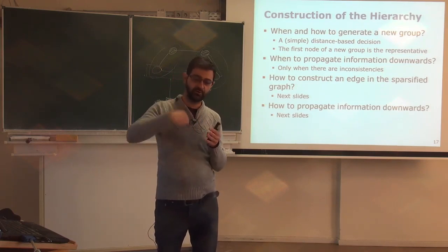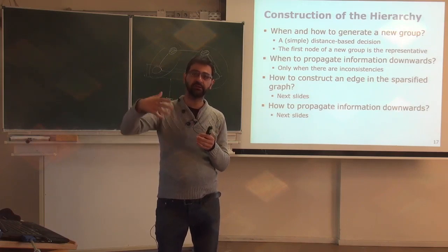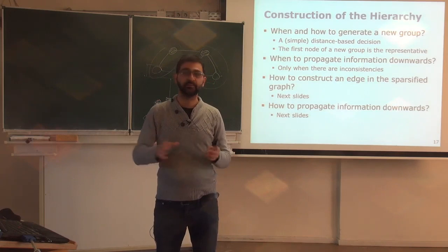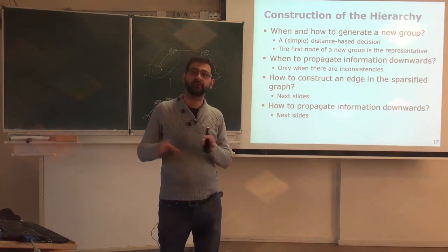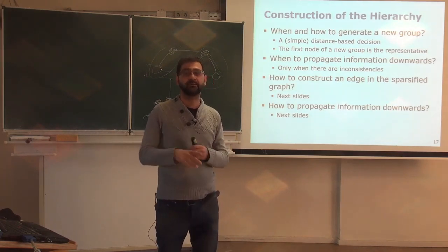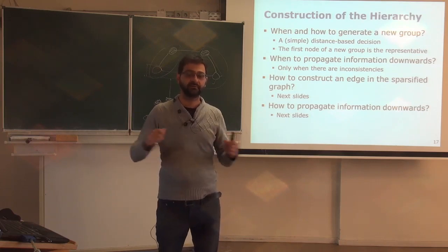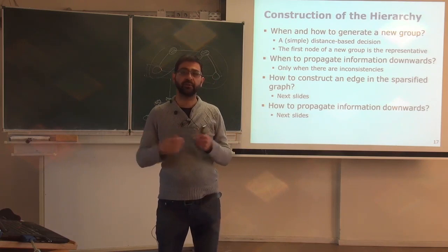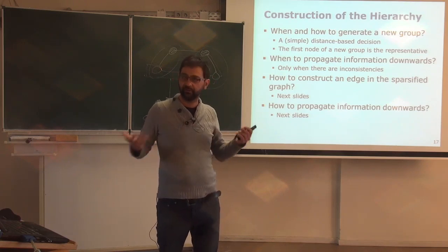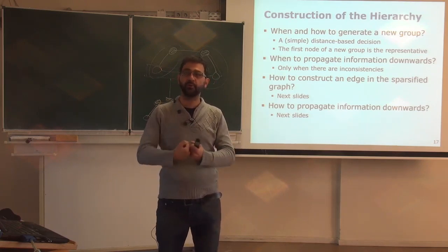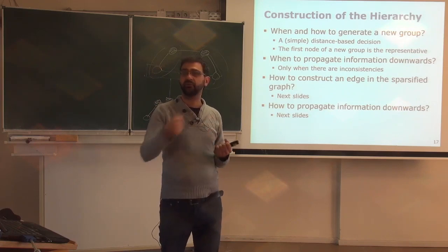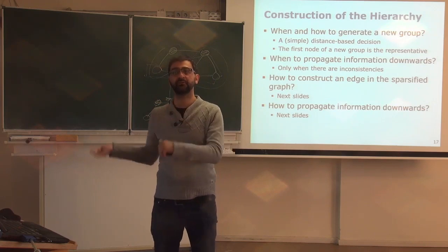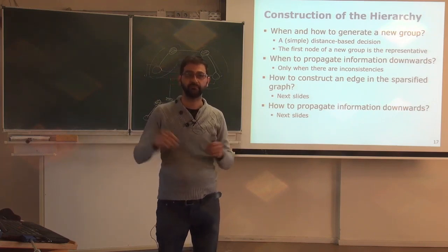Since we are building this graph incrementally when new observations come in and the robot moves, we just have a distance-based threshold. We say a cluster cannot be bigger than X. At some point, you close one cluster. Or if you start from the beginning, you take the first pose as the origin of the cluster, and you travel as long as you are not further away than X. Then you close the cluster and start a new one. Very simple.